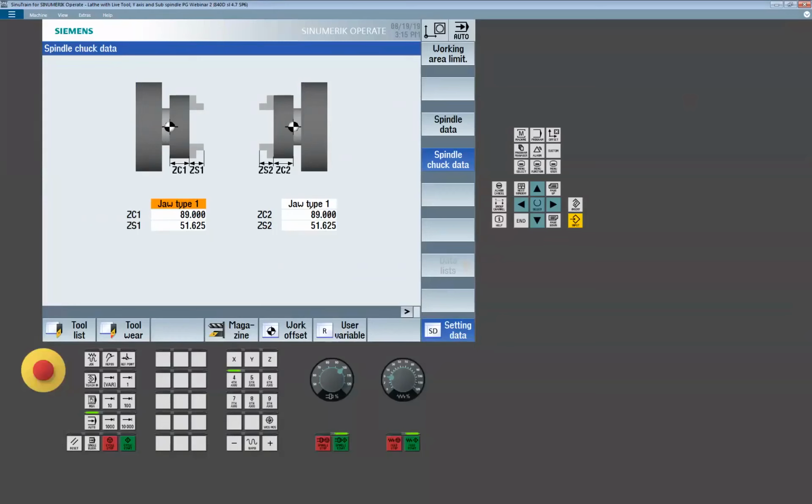So once you shut the coupling off command, you're still driving from the same 0. I've never seen a case where that did not occur. Like in your scenario, you've indexed at 180. You haven't actually shifted the 0 of the counter spindle 180, just the relationship of the two during the coupling command. All right, so any other questions from said audience?